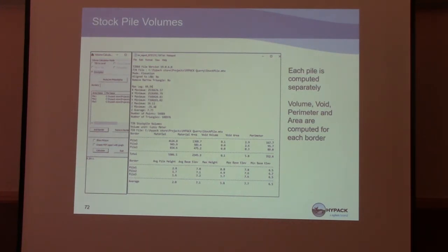But so is it just giving you elevations instead of depths? And like anything above, what it does, actually, this is where it becomes very neat. The border file becomes a cookie cutter, and then it cuts out the data inside the border file. But at the edges of the border file, it inherits the elevation of the triangles that it cuts, so that your template, your 0 base, is the edges of the cookie cutter. So if the bottom goes like this and your pile material goes like that, the bottom went like this around the edges where your cookie cutter was, that's the edges of your cut, not just a single flat cut. So it inherits the surface at that point, and then you just cut the volumes out of it.